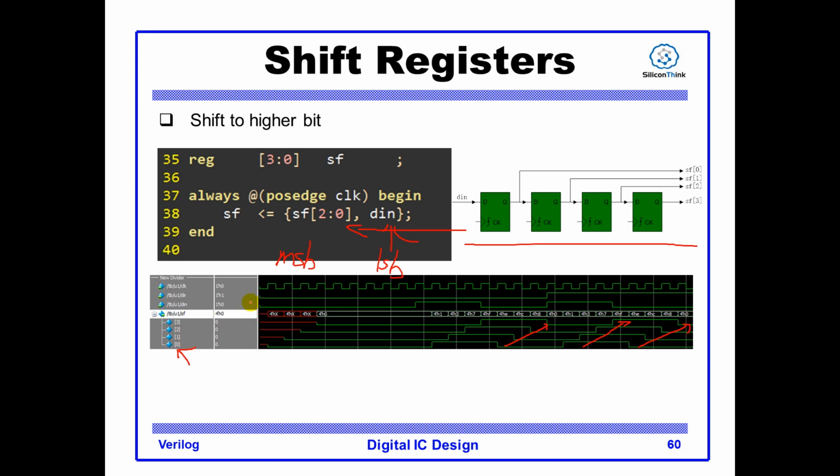Please note that if you use this Verilog tool to run the simulation, you can't see the unknown value at the beginning of the simulation. This is because this is a free tool. It's just a two-state value system, that is, it just has the value of 0 or 1 for each bit. It doesn't simulate the value of x or z. But other simulators such as ModelSim and VCS are 4-state value systems.